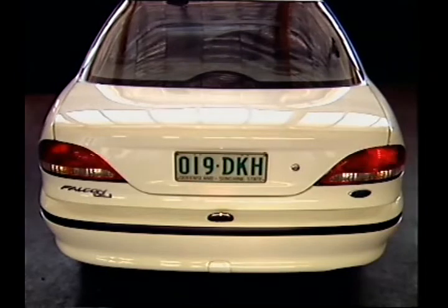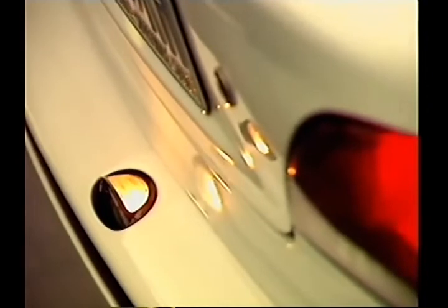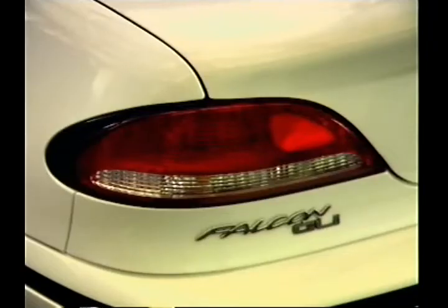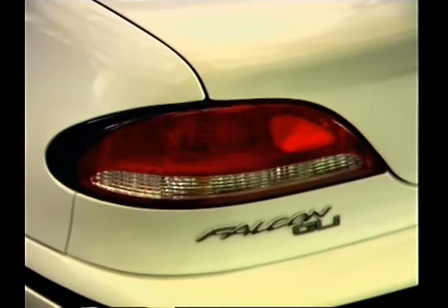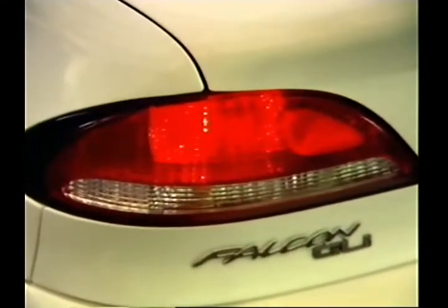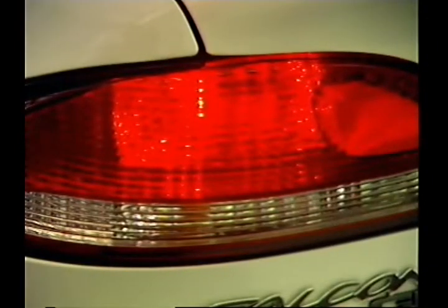The bulbs are connected in parallel to each other, so that the failure of one filament will not cause total circuit failure. A number plate illumination lamp is usually connected in parallel to the tail lights and operates whenever the tail lights are on. The tail lights are usually incorporated in a cluster assembly at the rear of the vehicle. Government regulations control the height of the lamps and their brightness.